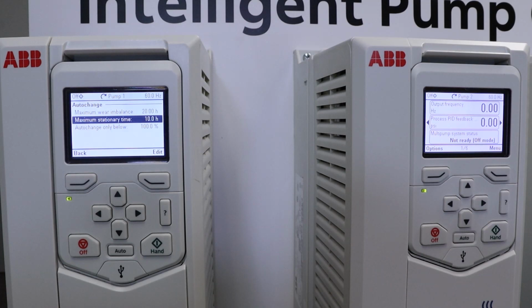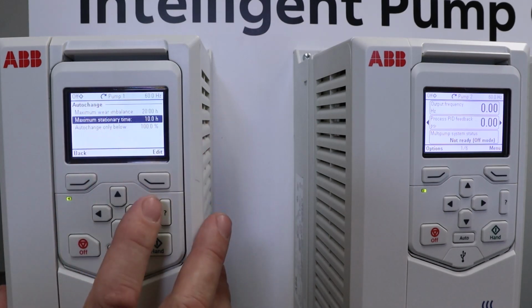That could be adjusted to like 90% or 80%, just so when you're doing a high demand scenario, you want to make sure you're below that demand when you're doing your auto change. But your auto change in our system actually does smooth auto changing. It will bring up another pump, and it will lower the pumps to even them all out and do the changeover. But these are the settings you can set.